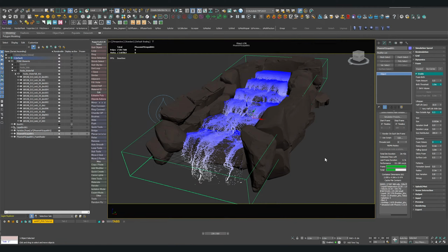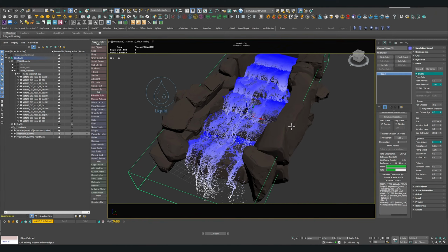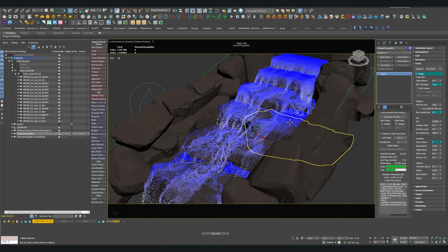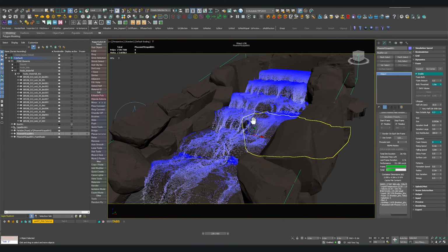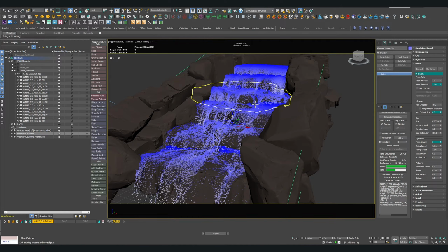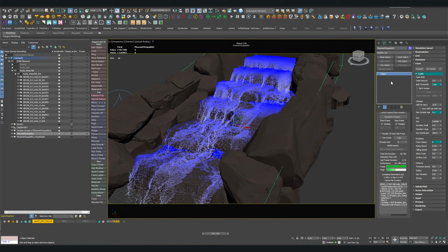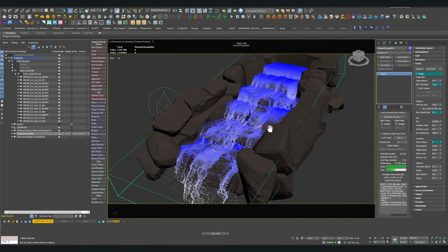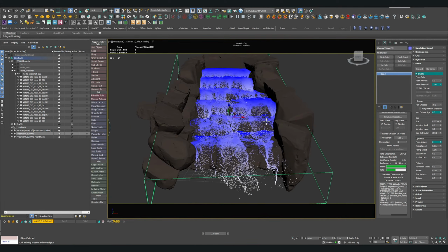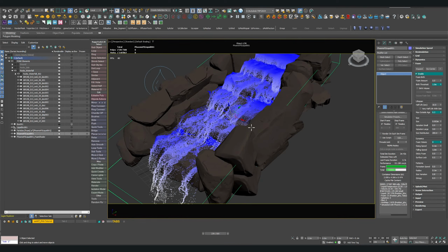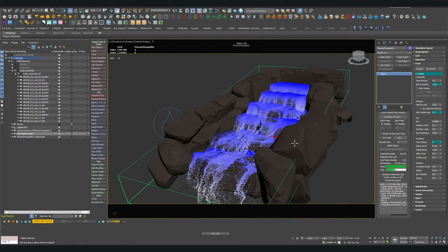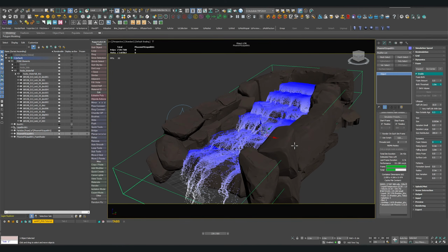So I stop the simulation right here because when I take a closer look at that, rarely any foam particles are getting generated, which means that none or nearly none of those blue particles is going faster than 1 meters per second, which actually is a good thing to know because that means that we have a nice flow of our fluid, which is not fast and not too slow.